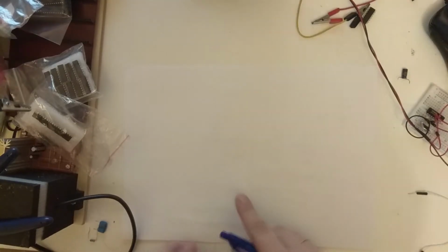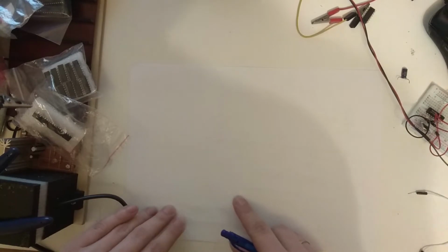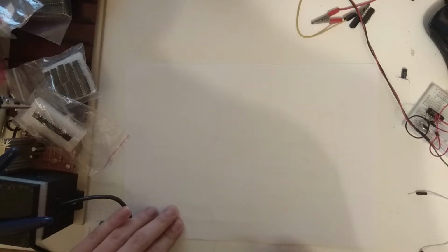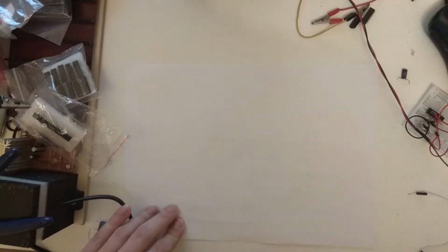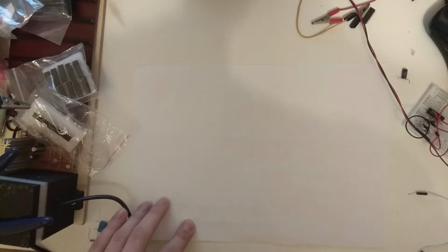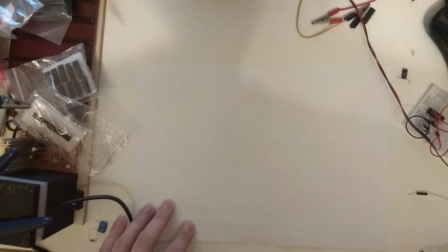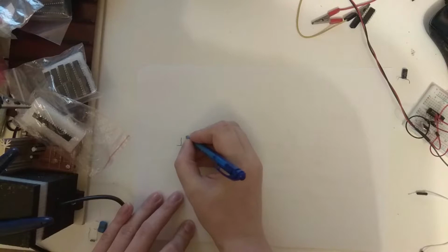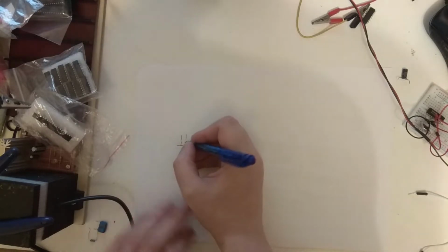The second part of this board that we're going to design is the reset circuit, and I want something that, as I said before, does automatic reset on power on, and also does manual reset if you press a button, if something has gone wrong. And how we're going to do that is with a Schmitt trigger.